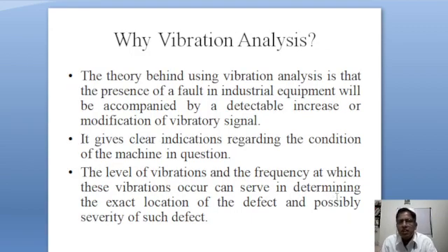Now we will see what is vibration analysis. Whenever there is a deterioration in the machine, the vibration signals associated with the machine also increase, and by analyzing those vibration signals we can detect the presence of a fault.